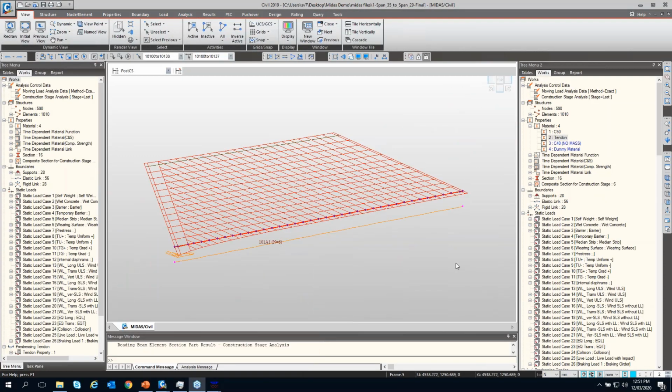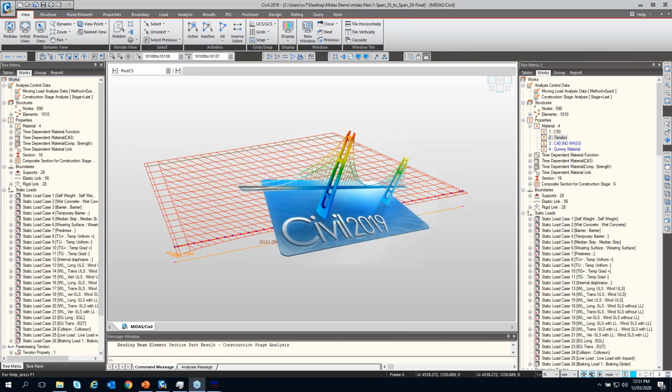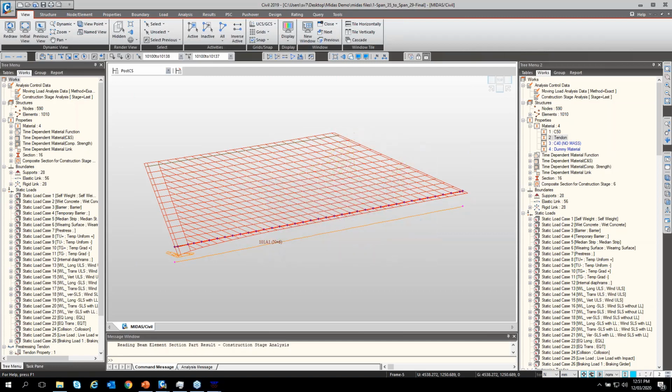In the meantime, I can take some questions if someone has any. Yeah, in composite sections, do you give density to slab sections? In composite sections, we do not have to give a density to the slab sections because we are applying it as a UDL on the girders. So if you give it a density equal to the density of concrete, again, it will be a duplication of loads. So just be careful not to give the density of the concrete deck. Just give it 0.